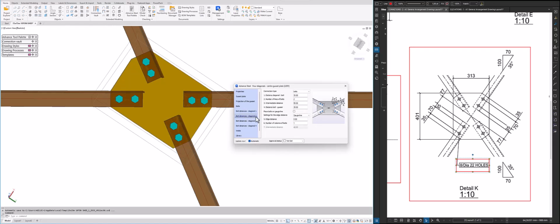All right, so guys, let's do the same for the rest. That is 70, and then center line, that's 70, and we change to the center line, and then lastly 70, then center line. All right, then we are set with this connection. So from here, welding, default set, everything is all right. Library, don't need to worry about that.